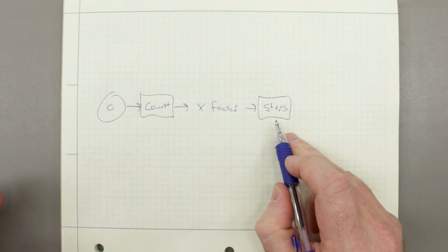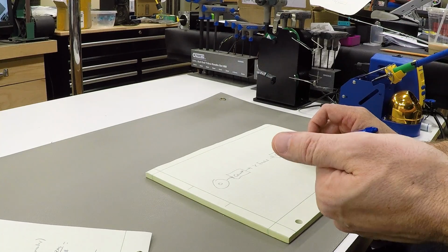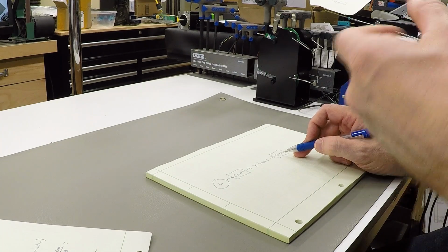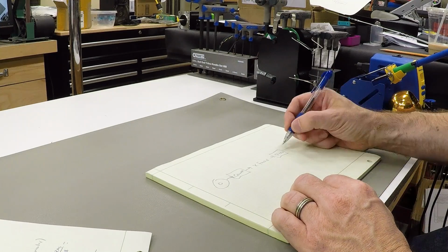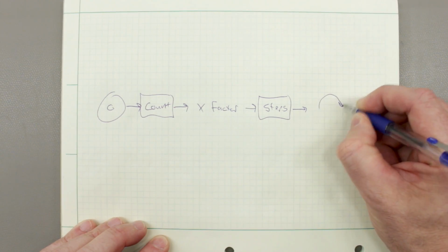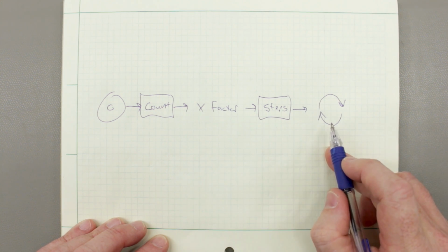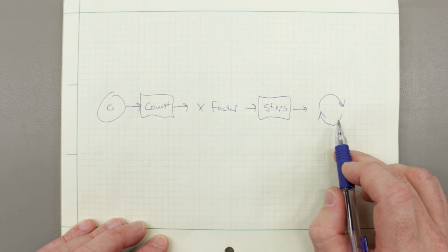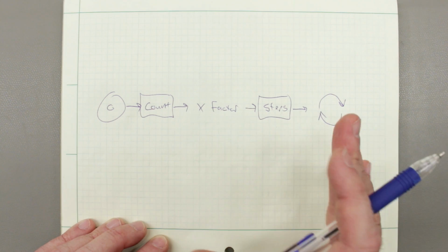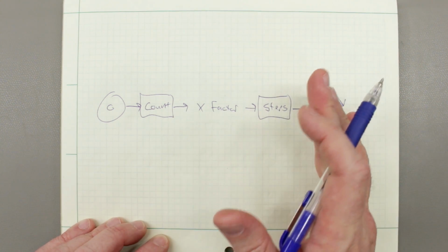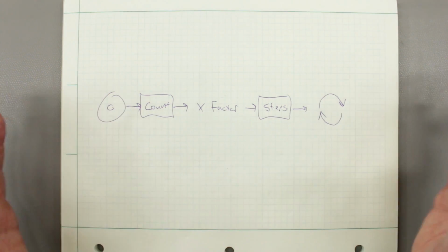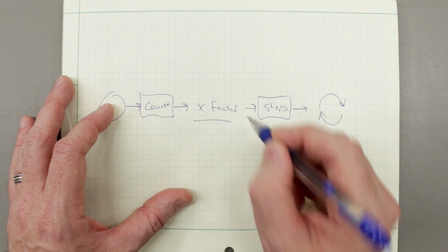Number of steps to output to a stepper motor or to step input on a servo driver. And then that number of steps is fed as input to a control routine that actually drives the stepper or the servo to that position. So the important thing to figure out for any scenario with any particular lead screw, with any particular thread or feed is, what is this factor?